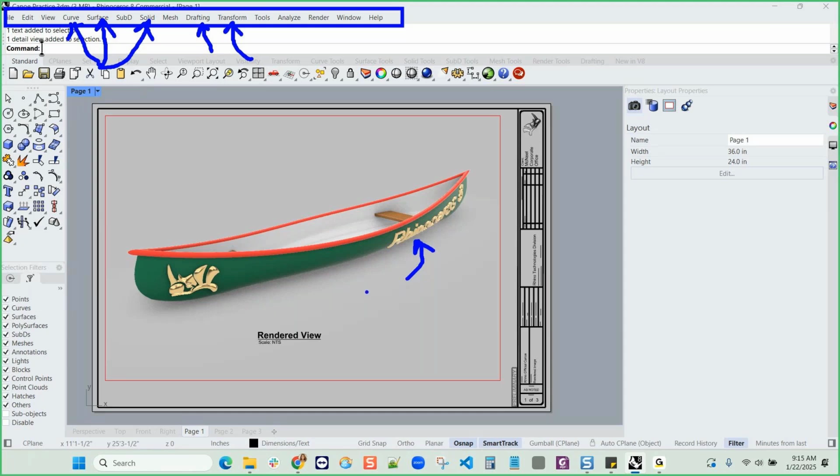And that's because of the flow along surface command. And same with this Rhino logo. The Rhino logo was designed planar on the XY construction plane. And then we picked up the Rhino logo and flowed it along that surface. You can imagine how much more complicated this would be if you had to design on this curved surface.